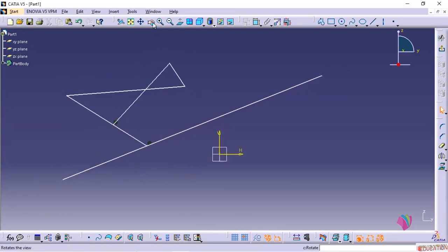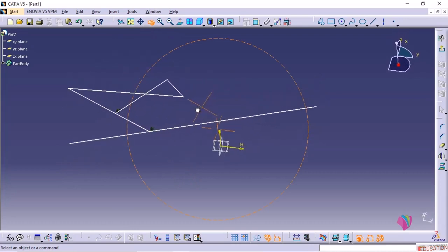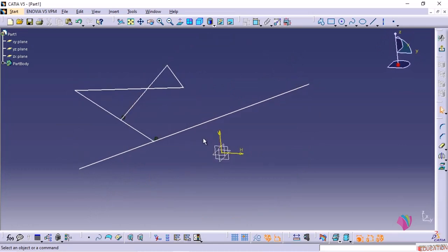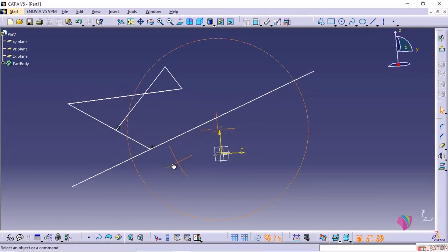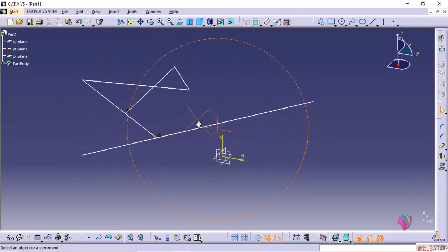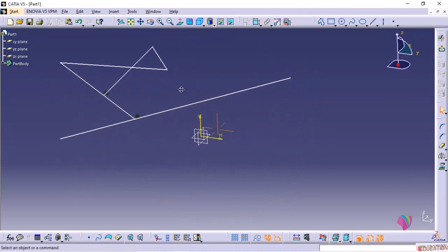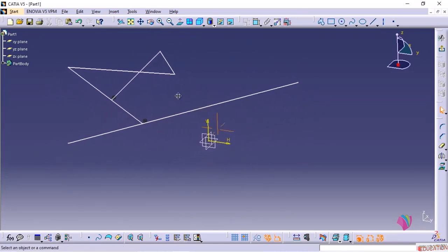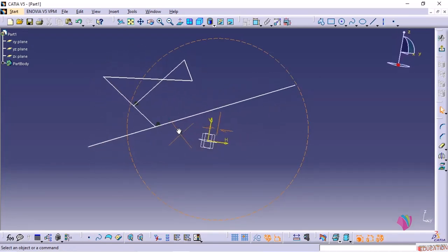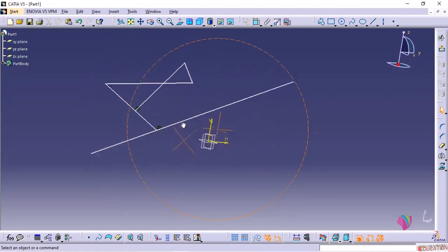Next thing is rotate. You click on this icon which is rotate. You have to press the left click and move the mouse. You can see it is rotating. The shortcut key for rotate in CATIA is, you have to press the scroll and the mouse right button and you can see this is rotate. So, if you press the scroll and move, this is pan. By keeping the scroll button pressed, just once you right click and you can zoom. If you press the right mouse button and the scroll at a time, keep them pressed and move the mouse, this is rotate. So these are the shortcuts.